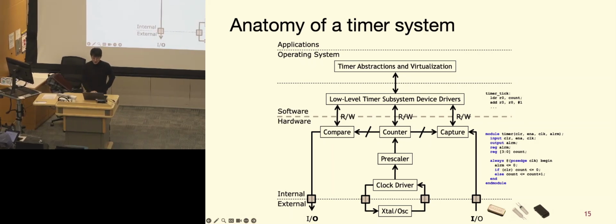And then we also have the virtualization of the timer. This virtualization is a software technique that allows multiple applications to share a single hardware timer. It basically provides a virtual timer to different tasks. Again, this is a very convenient way to have only one timer, but use it to control multiple different applications or devices at different frequencies. So this is the virtual timer here.